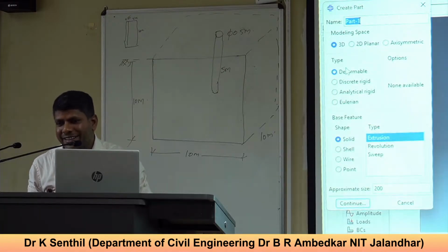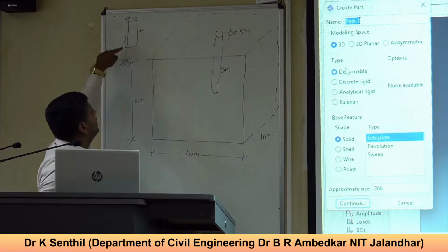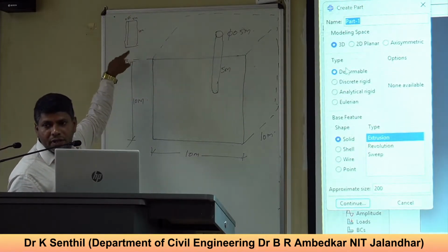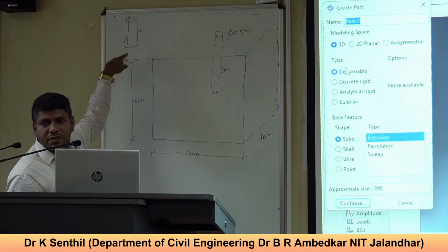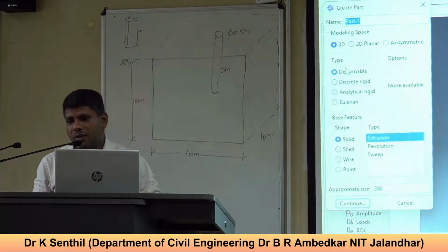Yes. In that case you can define the boundary conditions, and maybe here it's purely zero depth. Because you have the soil that is trying to flow around the pile when you apply the lateral load. Okay. So the best you can probably do is to take an axis of symmetry through the middle of the pile. Yes. But even then, the other direction becomes a problem. That's why people think.